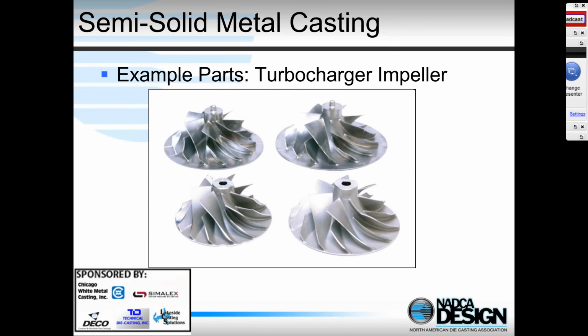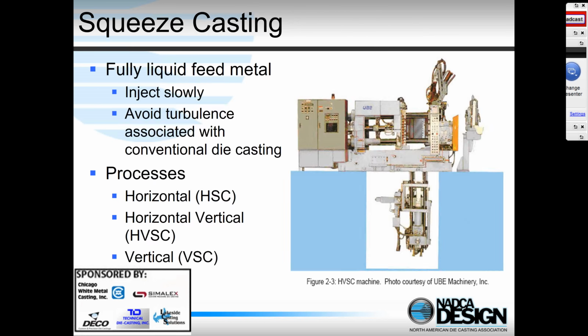It's a fatigue application, very, very important fatigue, and so generally porosity is really bad for fatigue in metal castings, and so a turbocharger has to have good fatigue life, and therefore we produce some by semi-solid casting.